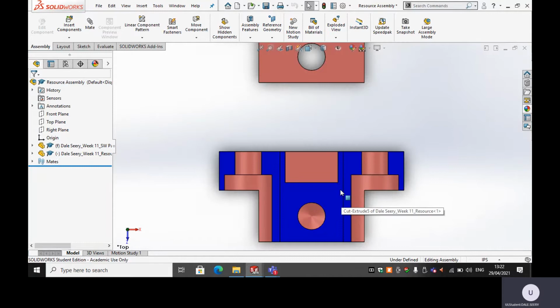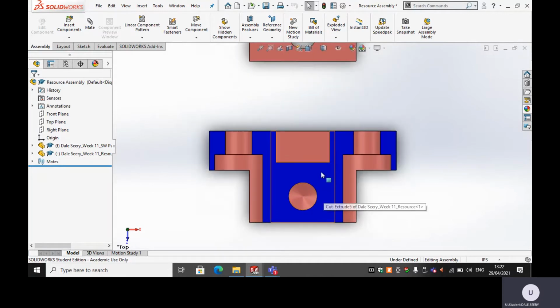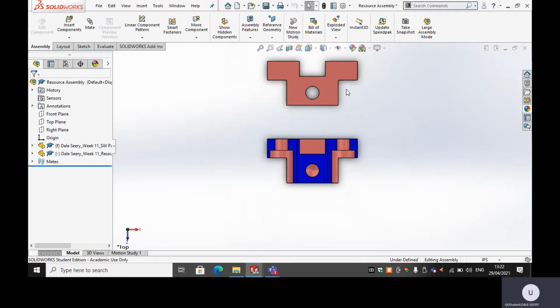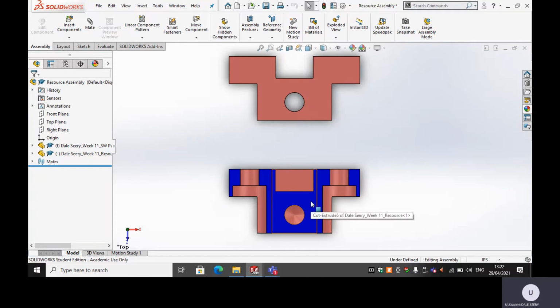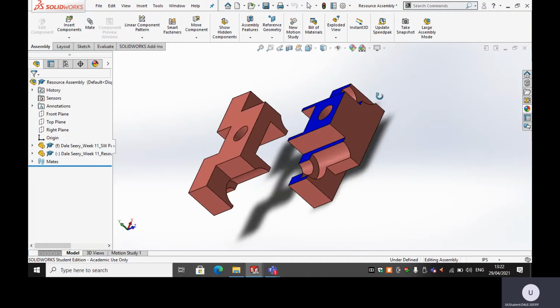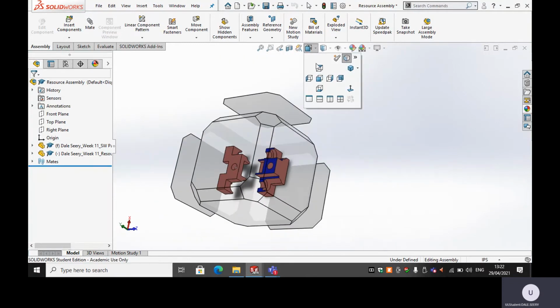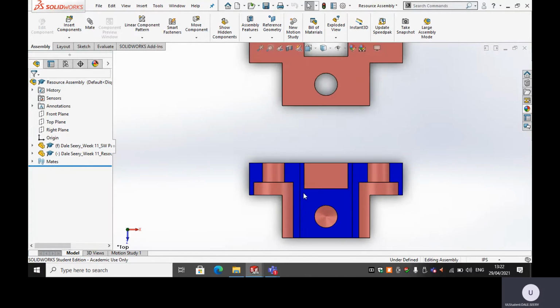So this is the offset section, and I'd be showing them that on the drawing it shows the hatched lines, and explaining to them that this blue section would be the hatched lines. And what I do myself to try and make it easier to understand is I like to think of the blue line. I like to think that if this part was cut straight down with a saw, some sort of a bandsaw, the blue lines or the hatched lines that appear in the drawing would be the point of contact that the saw would make with the part.